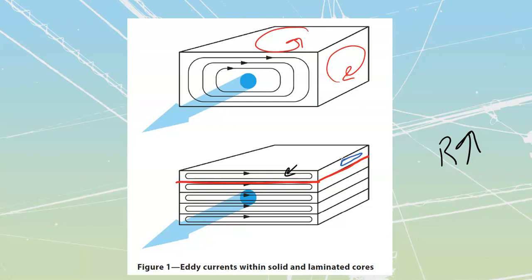We do have silicon steel as well because it also has a high permeability. And permeability is just the ability for flux to flow. The higher the permeability, the more flux that we can fit inside of any given type of object. And we want to maintain as much flux as we can inside of the transformer core, because that means it's going to be aligned right next to my transformer windings, which means that we are going to cut through more windings. We're going to have, once again, more efficient transformation.